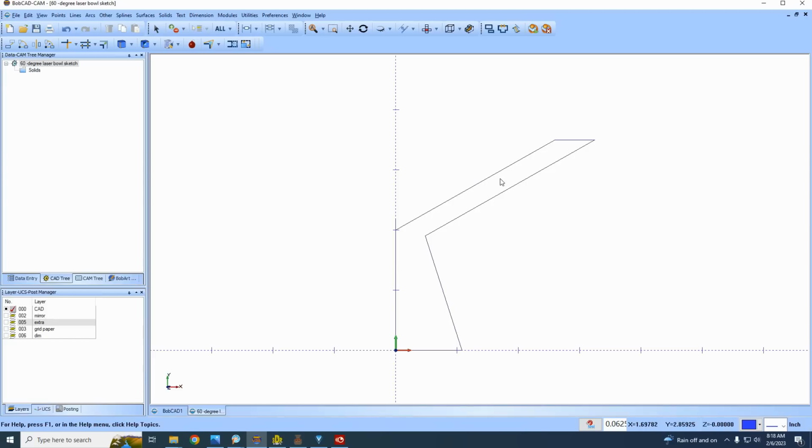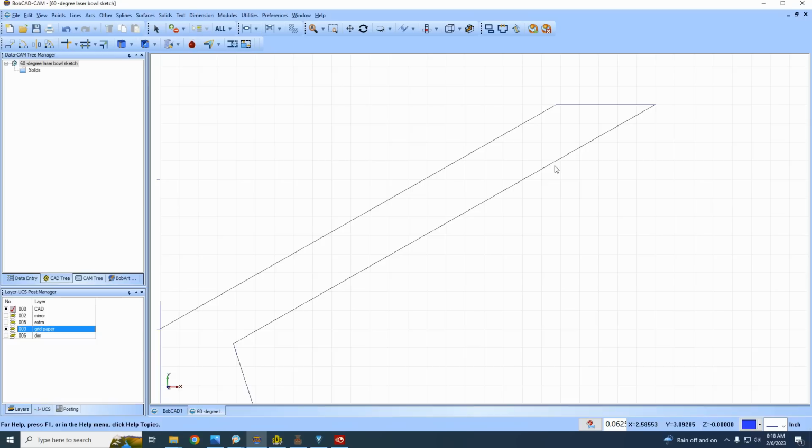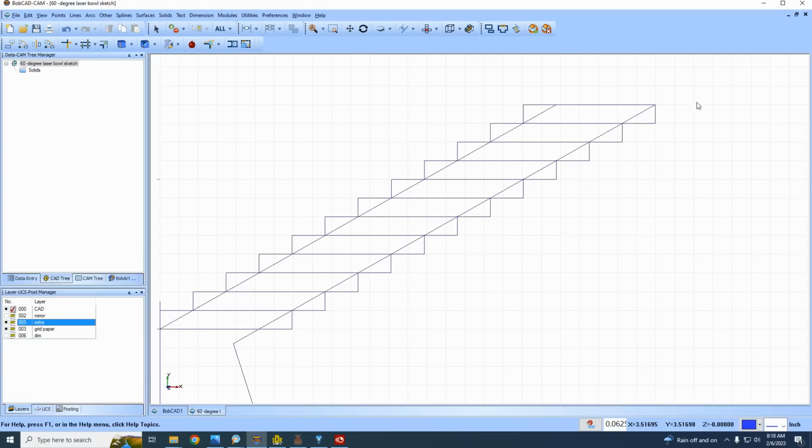So this is nothing more than some straight lines, similar to that bowl I talked about. How would I draw this up and get accurate and figure out segments from it? You do it on a piece of grid paper. Okay, I'll zoom in here. See these little grids? You could draw your shape on here, and let me see, I'm going to add segments to that. And then you take horizontally and you come across here, and where this line intersects the wall, the inside wall, outside wall, you draw a line straight up to the top, straight down to the bottom. You now have your segment right there.